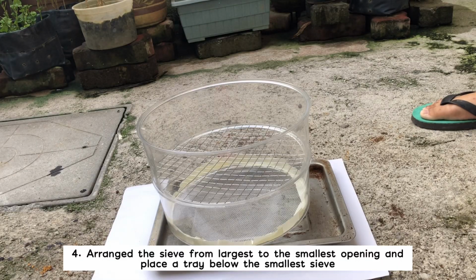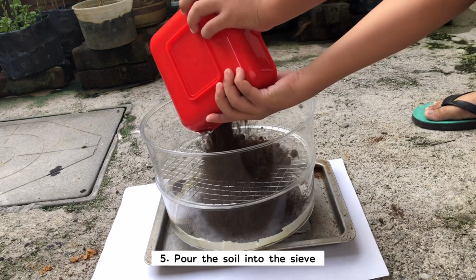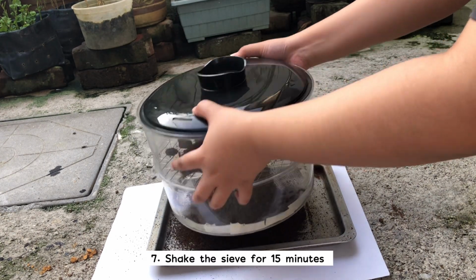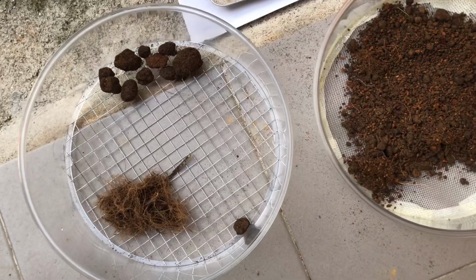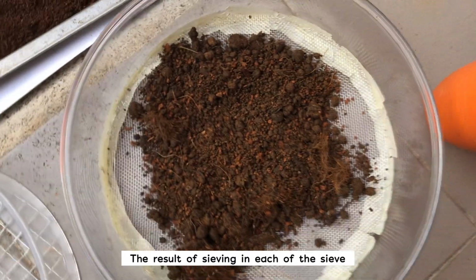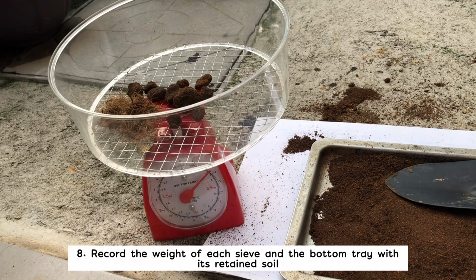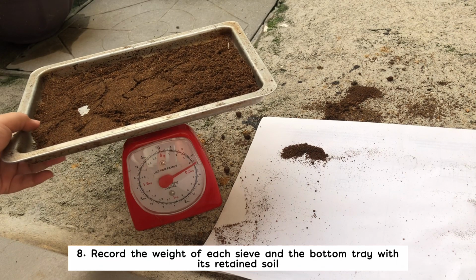And then for the fourth step, arrange the sieves from largest to smallest opening and place the tray below the smallest sieve. Pour the soil into the sieve and place a cap over it. Next, shake the sieve for 15 minutes, and record the weight of each sieve and the bottom tray with its retained soil.